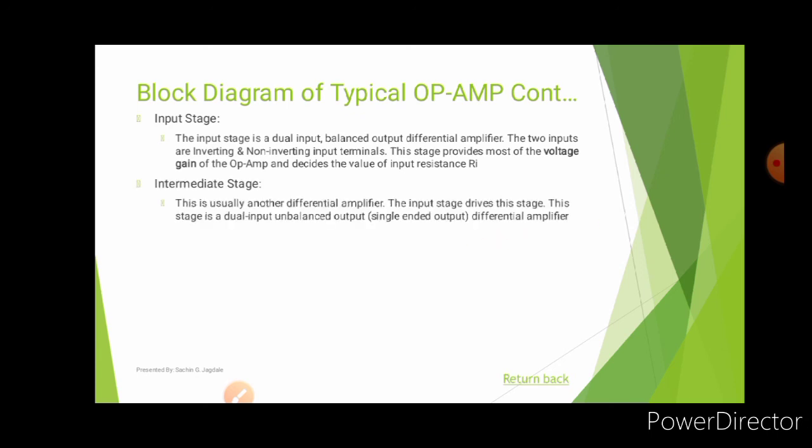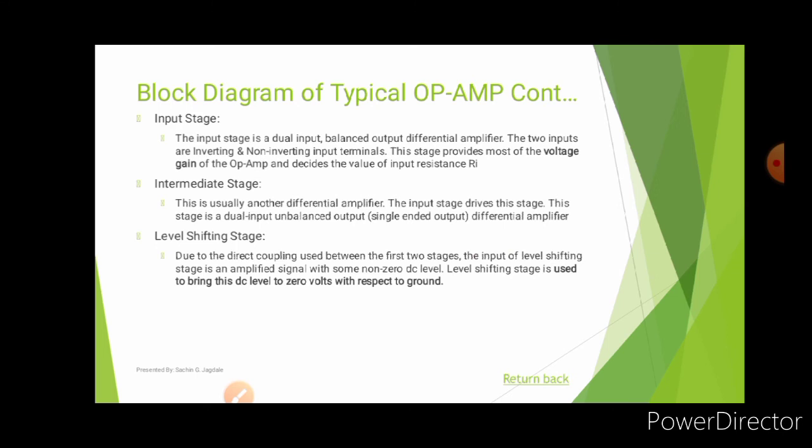The second stage is the intermediate stage. This is usually another differential amplifier. The input stage drives this stage. This stage is a dual input unbalanced output, that is, a single ended output differential amplifier.